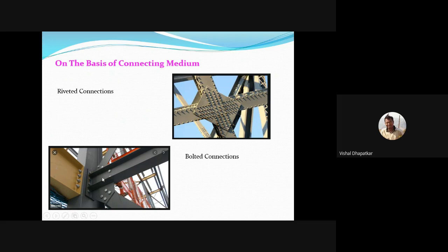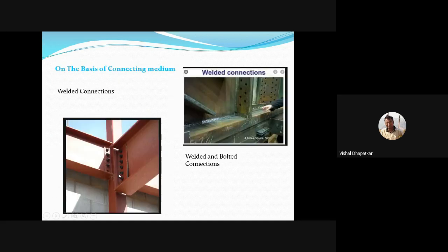So it is an easier method and also good practice to use bolted connection because it provides flexibility, and also we can achieve the required connection type. If we provide welded connection, then some part of fixity will get developed, because of which there could be a transfer of moment, right?